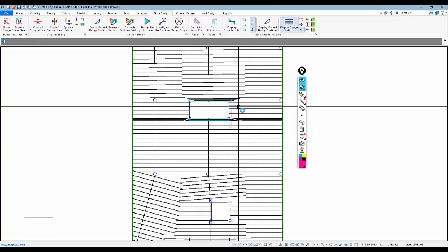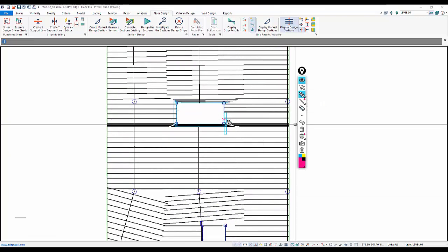Now, one thing we do want to avoid is having a design cut extend over a wall, like here and here. When that happens, you can see that the support line is actually over here on this column line. These reach all the way over and extend over the wall. If a design cut extends over a wall, we don't design the cut for ultimate level demand, meaning for strength combinations we don't produce any reinforcement. We only reinforce these cuts for minimum reinforcement.